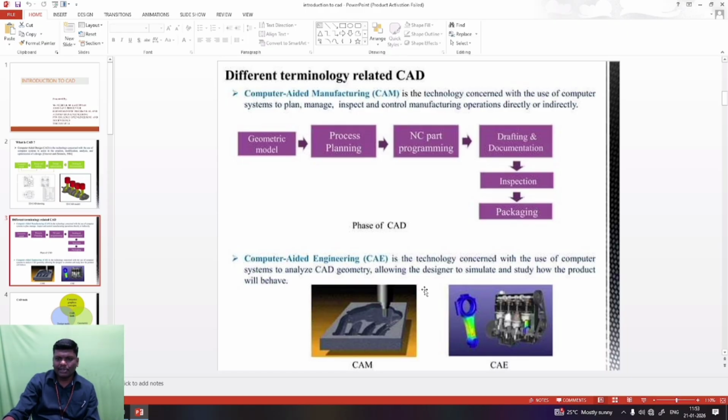So it will simulate the product. If you see the piston head, there will be a blue mark, a green mark, a yellow mark, and a red mark also, light red. This is the color coding of impact, because blue is mild damage, green is no problem, yellow is medium damage, and red is a critical condition.